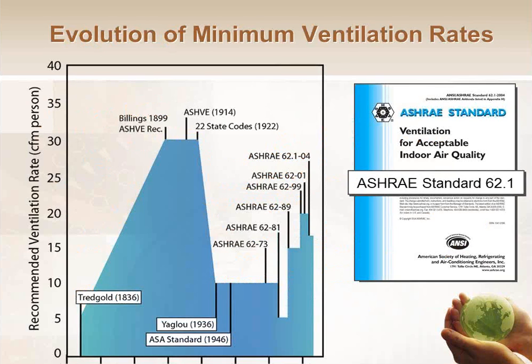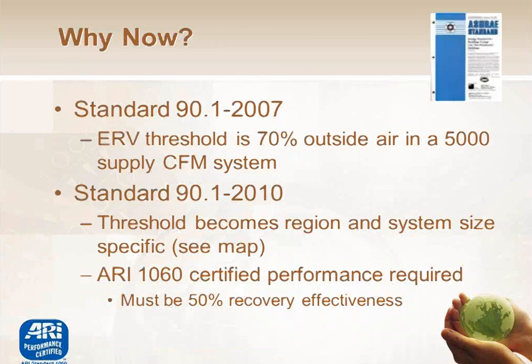So that shows you our historic ventilation rates over time. And as I said, anything built after World War II was probably designed with 10 CFM per person in mind, maybe 5, maybe 15, but pretty much anything between World War II and the end of the 1990s was designed with 10 or 15 CFM per person. And nowadays, most of the codes are going to average out to be around 17 CFM per person for an office building type example. So we need more outside air than we used to when we retrofit these buildings.